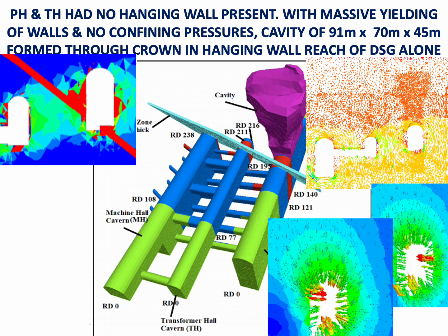The dislodging of the key rock blocks from the walls at the SPL supporting the crown in the Downstream Surge Gallery provided the much awaited trigger for setting in the action of instability in the arch and eventually for the fall of the crown of the downstream surge gallery, in which loose rock blocks were already subjected to tensile forces.